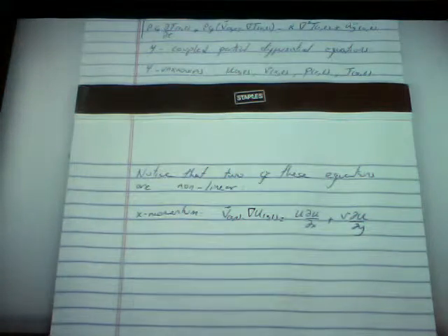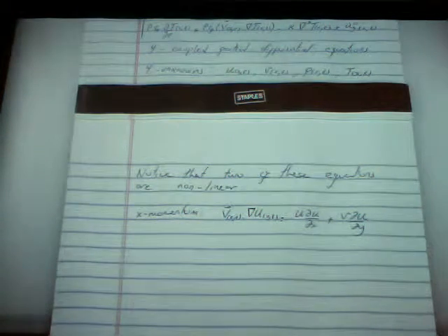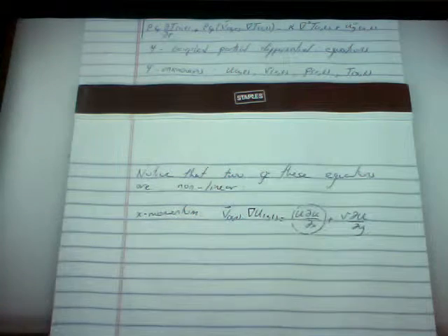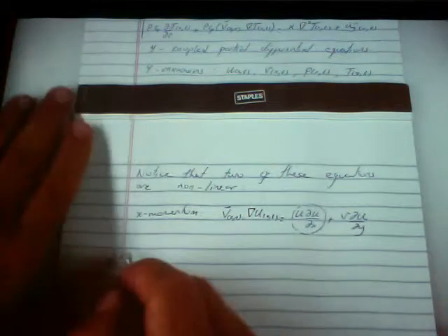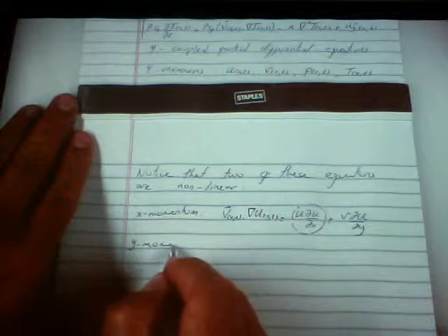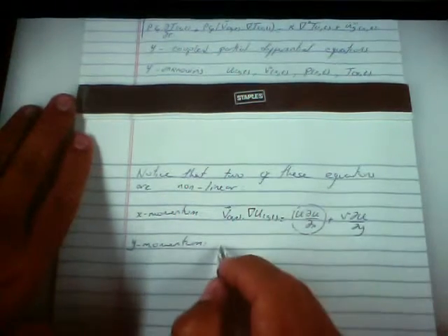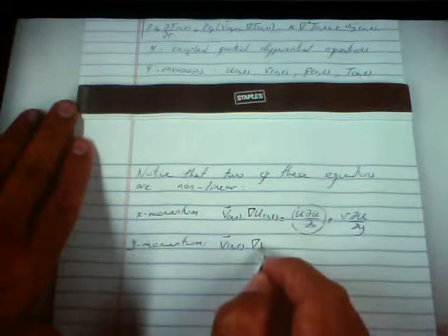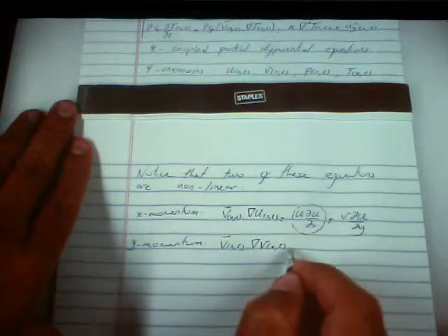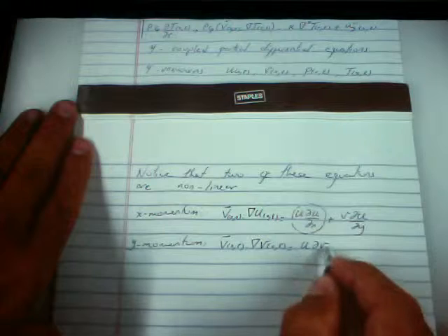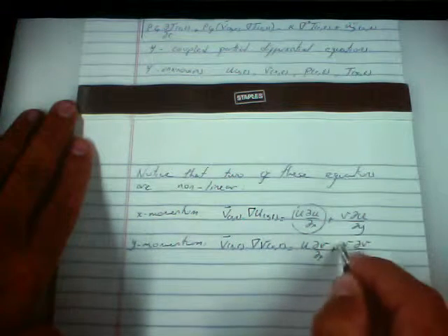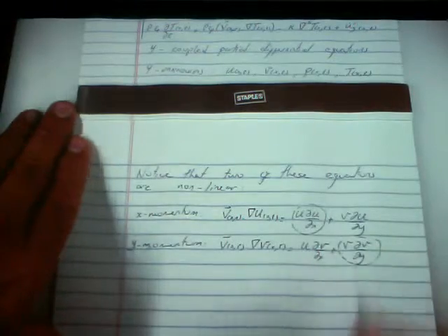That's how we expand that term in 2D. And this is nonlinear. We have U multiplying the derivative of U. And the y momentum equation, V dotted into grad V, means that U dv dx plus V dv dy. This is nonlinear.